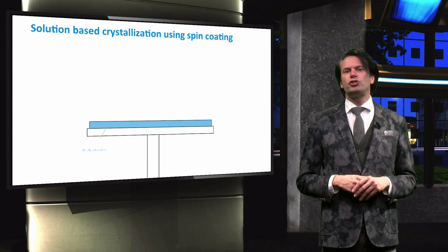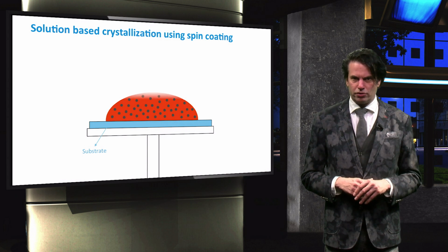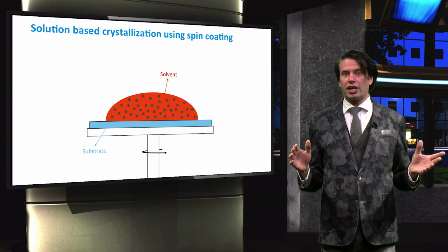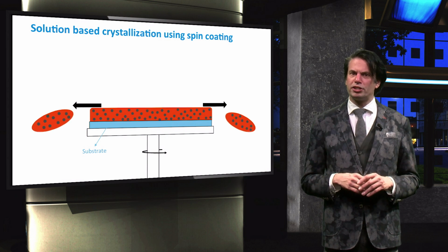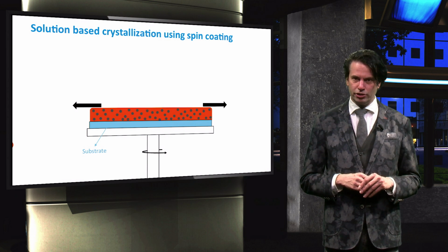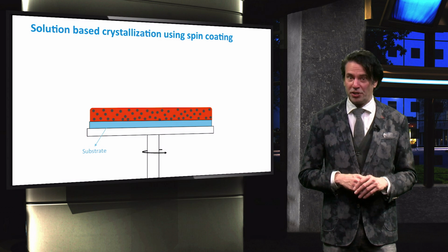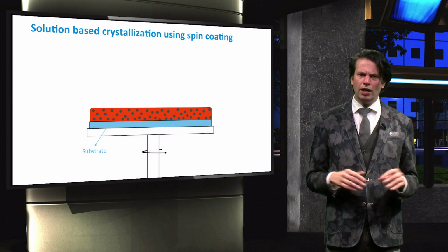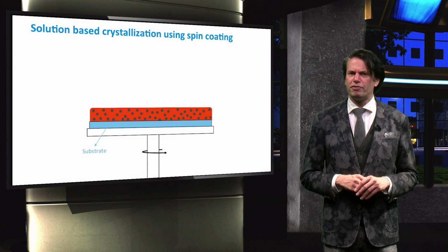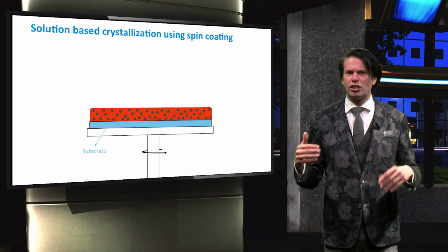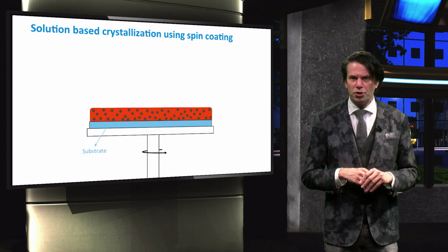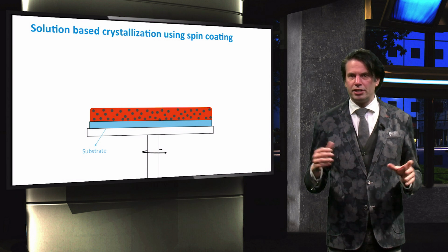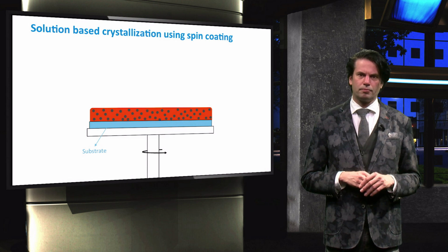Perovskites can be deposited using several processing methods. Various deposition technologies can result in high-quality perovskite films. The method most explored is solution-based crystallization using spin coating of a precursor solution. Processing has been further developed and post-treatments have been successfully applied in which anti-solvents, methylammonium lead iodide, or an intermediate compound are used.